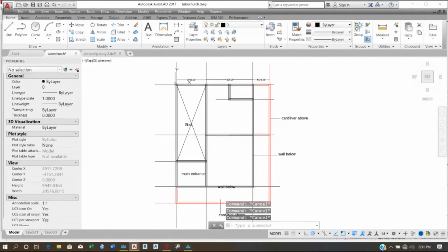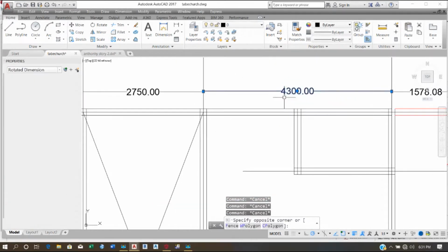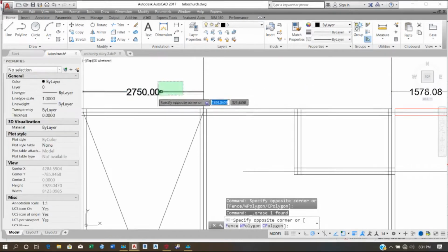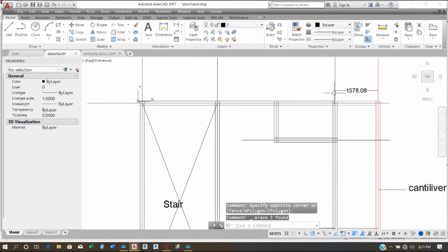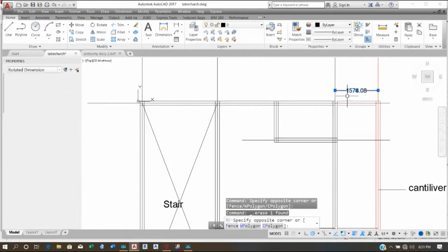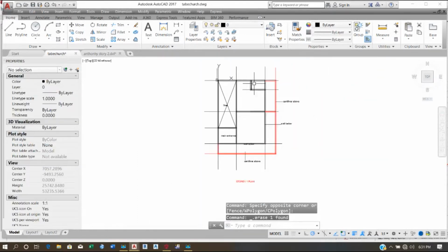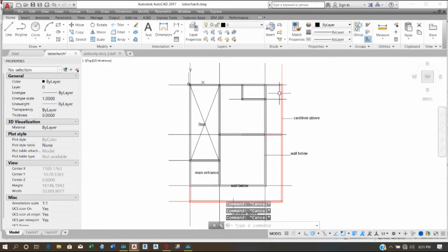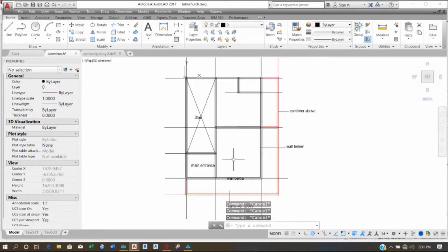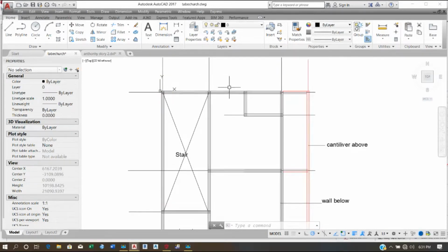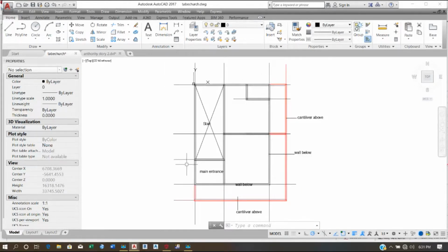The first thing I'll do is to create my general arrangement. General arrangement entails showing positions where columns and beams are going to be placed, and staircase and all of that. So this is my general arrangement. I have slab panel 1, 2, 3, and 4, as the case may be. I position my column and then position my grids for easy axis generation in Prota Structures.